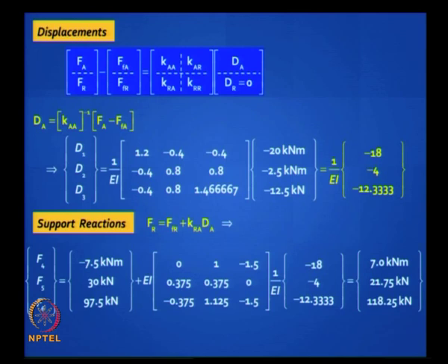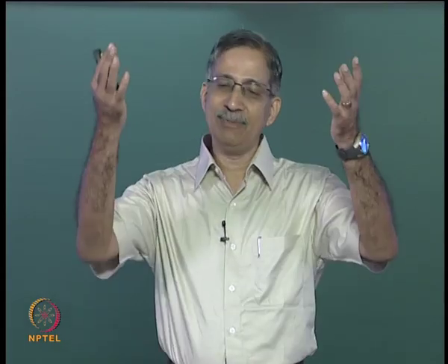No, before that you must check equilibrium, and it's a simple check. You can do many checks. You can do a moment equilibrium check, but the least you can do is add up the total downward forces, which must equal the total upward forces, and it's exact to the third decimal place in your solution. Then you find the member forces.